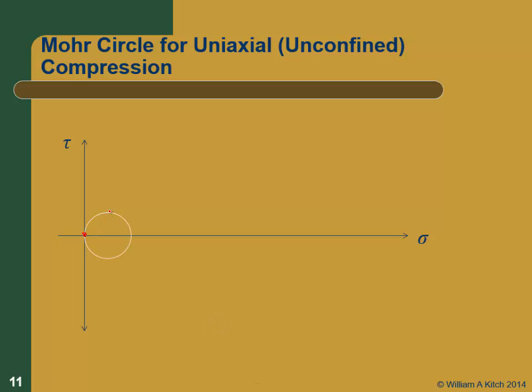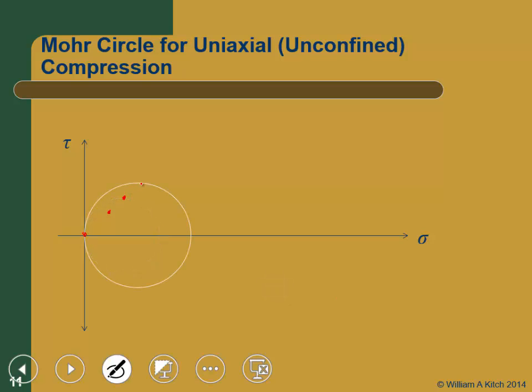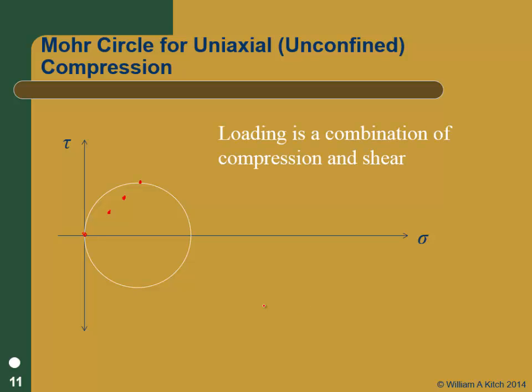I'm going to plot the tops of these Mohr circles for a reason I'll show you in a minute. And if I increase the load a little more, I get a different Mohr circle. Notice that nothing's changing down here. The horizontal stress is still 0. I want to plot that little point right there. And I keep doing this. And eventually, it'll fail, right?